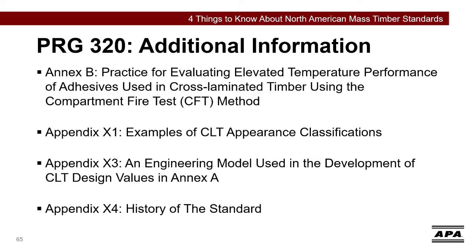Beyond Annex A, there are a number of additional sections at the end of the standard I wanted to quickly touch on. Annex B introduces the compartment fire test, which is a rigorous 4-hour simulation that verifies adhesives in CLT remain structurally sound under an applied load and full fire exposure. The adhesive must prevent char layer falloff, also known as delamination, which would result in fire regrowth during the cooling phase of a fully developed fire.